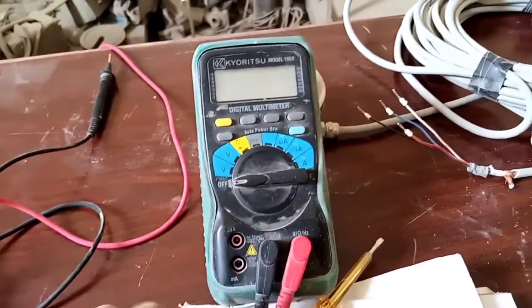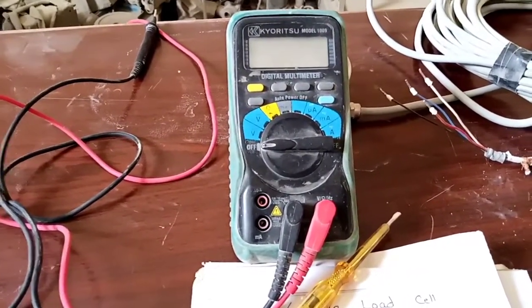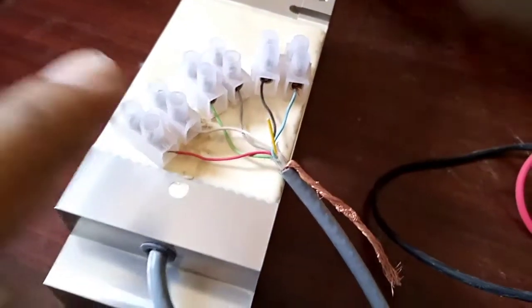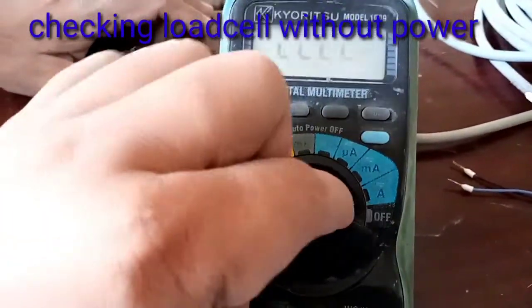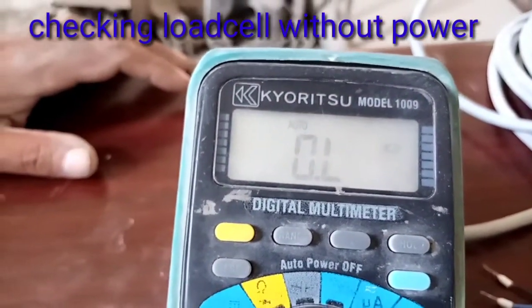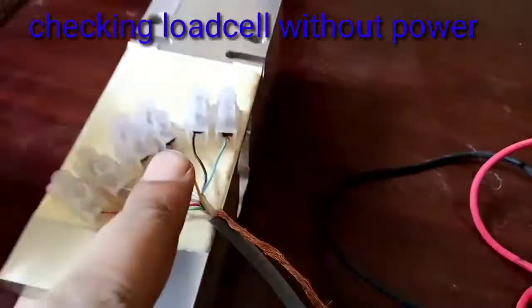First of all, we check the new load cell, how to check its resistance with a multimeter. A friend helped us for this purpose. Now this is our output terminal, input. First of all, we change the knob of the meter to the ohm position. You can see here, open meter wires. Now we first check the black and blue wire, its input resistance.